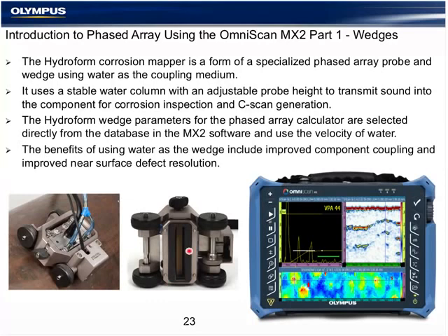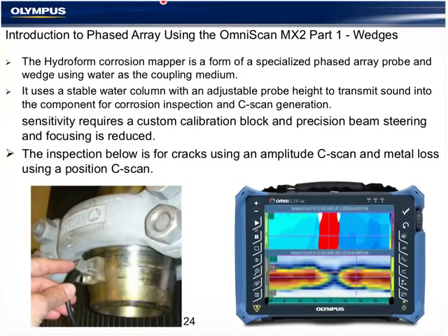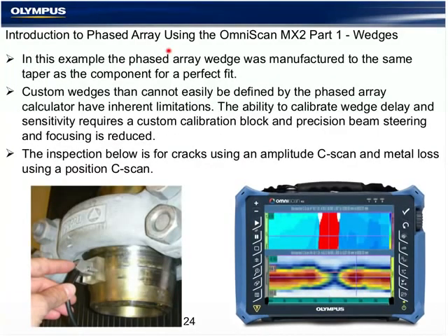And it allows us a feature often used in immersion tanks called a floating gate and echo synchronization on the A-scan, meaning that I can set a gate over the interface signal, and my other positions for backwall 1 and 2 become floating gates. And it gives us a lot of immersion tank functionality in a small portable system. The wedges are also designed to be custom made.